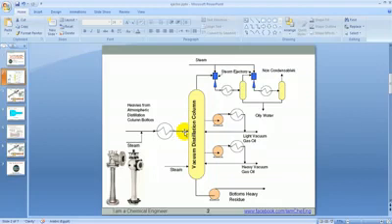So you use a vacuum distillation tower, which means that you will install these two equipments here. You can reduce them to only one steam jet ejector, but on most occasions, if you need more vacuum, you would use two steam jet ejectors. Placing the jet ejector is done at the last point of your system. Let's consider that our distillation column is our system. So you would put the steam jet ejector at the last point of your system. This point must have only gas. It cannot contain any liquids or solids, for that matter.